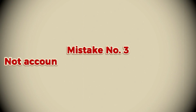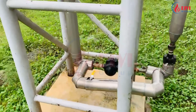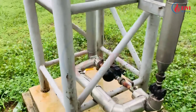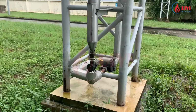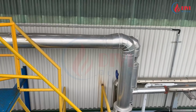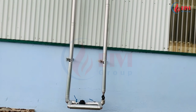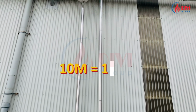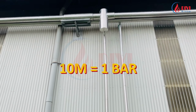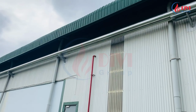Mistake number 3, not accounting for differential pressure, or not fully understanding the concept of pressure differential. When talking about ΔP, many people still don't understand it clearly. Let me explain briefly. The condensate pressure must be high enough to push the condensate through the steam trap into the main condensate line and send it back to the boiler. There are many pressure losses along the pipeline. If the condensate needs to rise 10 meters, then at least 1 bar of pressure is required. This does not include friction losses from pipe friction and elbows along the condensate return line back to the boiler.